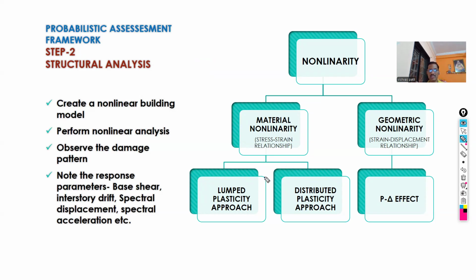Researchers have shown that whether you implement the lumped plasticity approach or the distributed plasticity approach, the seismic response results of the building do not differ much. So whichever is convenient to the user, adopt that particular method to assign the material nonlinearity.